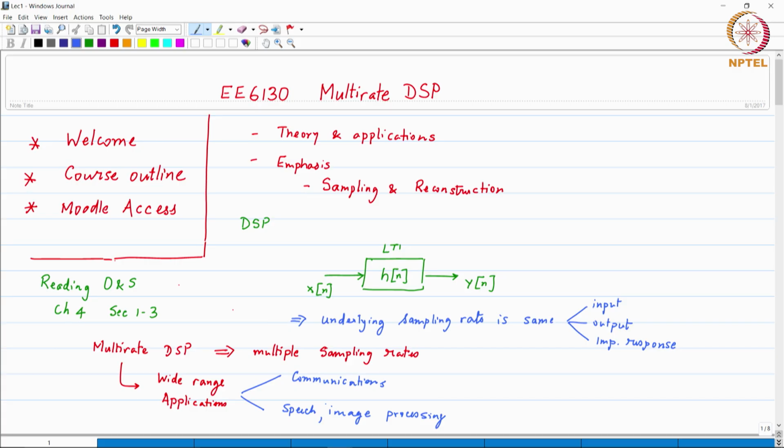How do you generate a transmitted signal? Multi-rate signal processing, you'll see, comes in many interesting flavors. But probably one of the things that makes it more interesting and contextual in the context of OFDM, in the context of communications, is that multi-rate DSP has one of its core components, a topic called filter banks, where you have multiple filters operating simultaneously on an input signal.